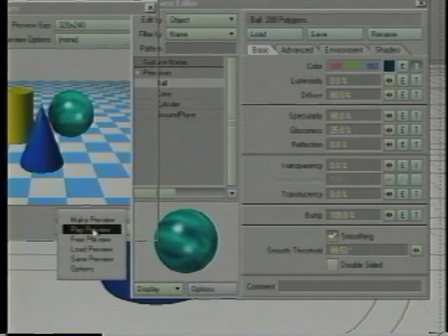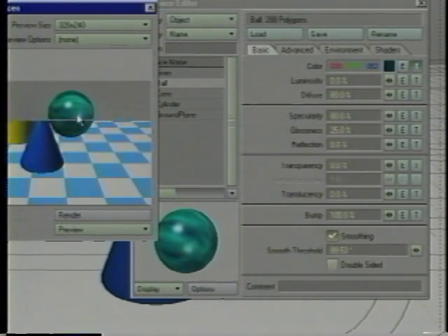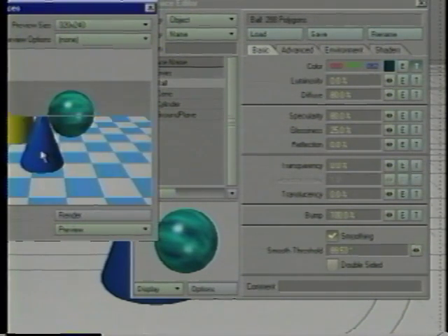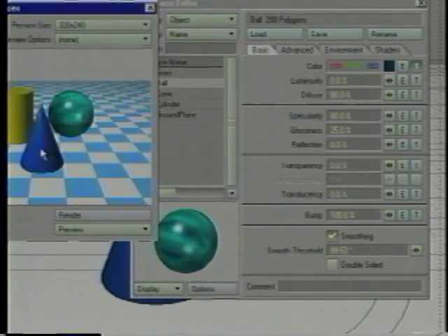And now we'll say Preview, and we'll let that generate. Again, notice that Viper's only updating the area that needs to be, so it's graying out the other zones, so we don't have to worry about it drawing extra data. This is a great way to test the speed of your texture or the direction of the texture as well. Looks like this one's going to be fairly subtle. There you can see it kind of boiling through as it moves through Z space on the object.